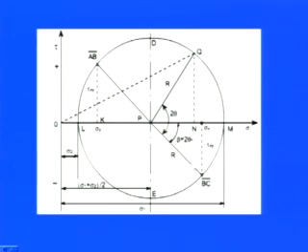So you can plot this either one way, or another way is to simply rotate this main axis where you see the sigma 2 and sigma 1. Rotate this part by beta, or you can see the 2 theta p where the principal planes are located, and then you can get those on the circumference of this Mohr circle. You can get both the values of both the points of the principal planes.